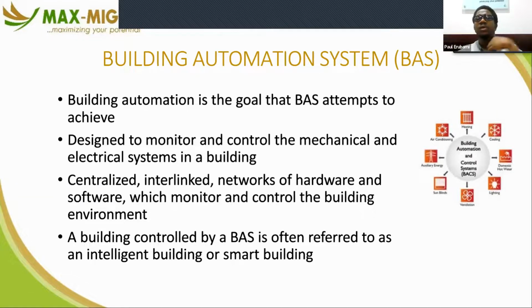So if I see the CO2 level, for example, being on the high side, which means the oxygen level is low, and that place is becoming uninhabitable for people, in a BMS system I would, remotely or from my central command point, open a certain damper. There's a valve that I can remotely control, or it's wired in anyway, so I can control that valve.